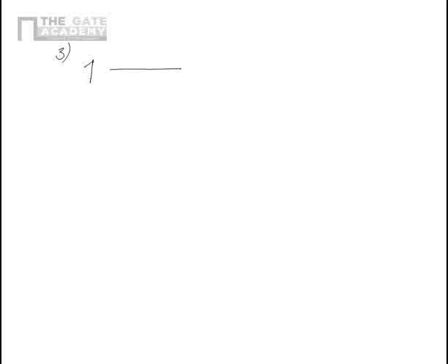Now let's see this problem. This problem is like this. We have a cantilever beam. This is the third problem, and we have here a cantilever beam in which the force is not applied at the free end. Please remember this and be very, very careful now. It is applied at the center of the beam at distance L by 2 from the fixed end, and L by 2 distance is free, which means there is no load applied there. I apply a force P here, this is P.